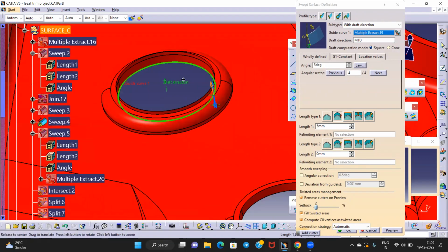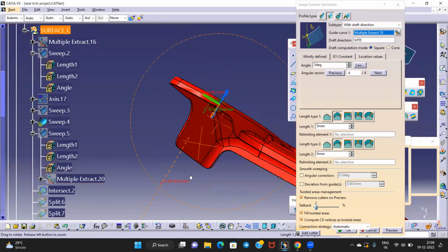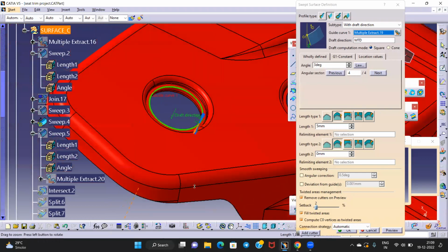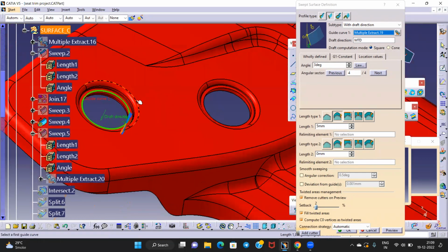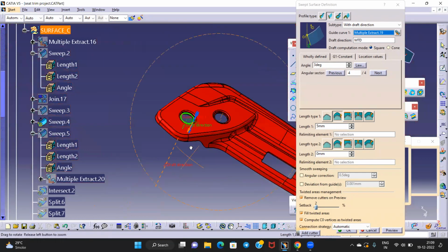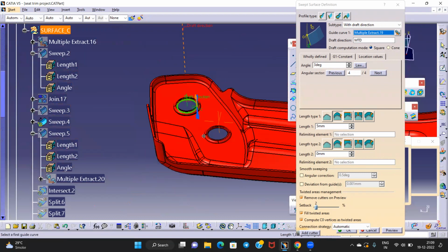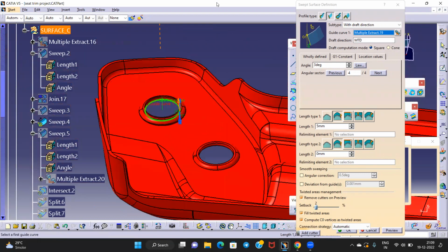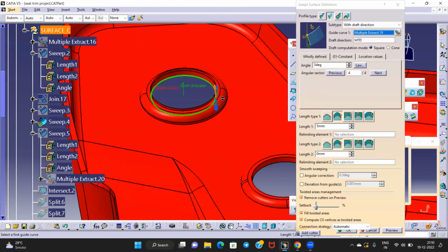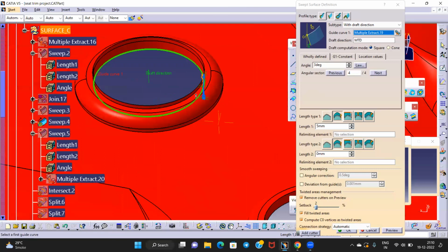Okay, parting line we are not keeping at the A side. We are keeping at the B side because this is a visible surface, right? So parting line will be visible from this edge. That's why we have to change. Did they understand what I am doing? Yes, Valraj, Anil, Viraj. Why I am changing the direction? Understood? Yes, sir. Yes, sir. So for parting line, I want parting line at B side. That's why. Rest is okay.